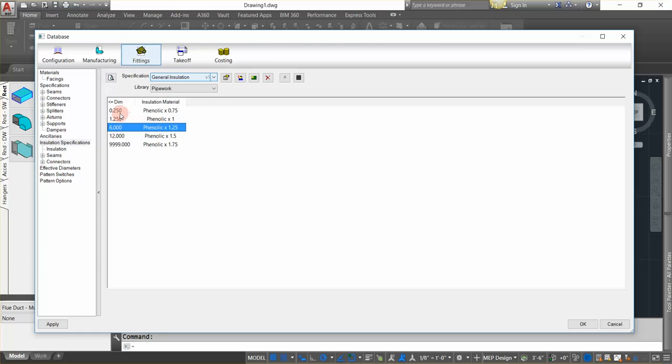And there's some thresholds set up inside of here. So basically this is saying 1.25 inch and under, use that 1 inch, 6 inch and under, that 1.25 inch roughly, and then above that it's getting 1.75 inches. Now it's not as detailed if we were to look at the steam. Not as much variance inside of there. Obviously we've got a lot thicker insulation being applied to it for those higher temperatures being used.